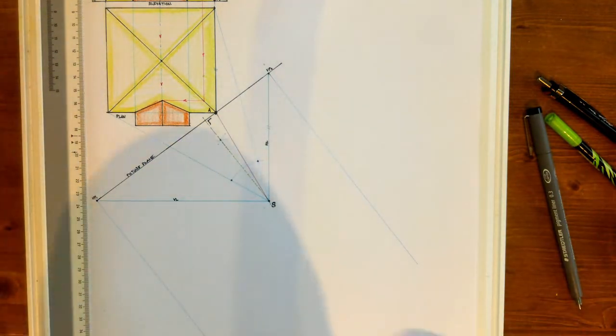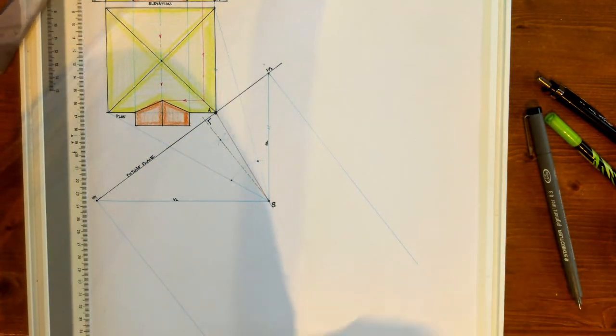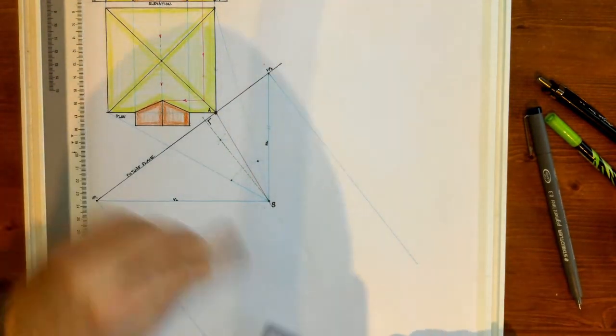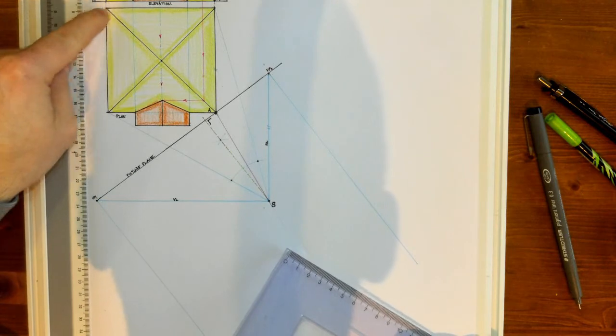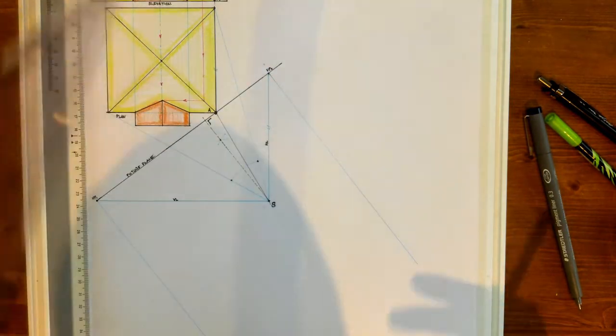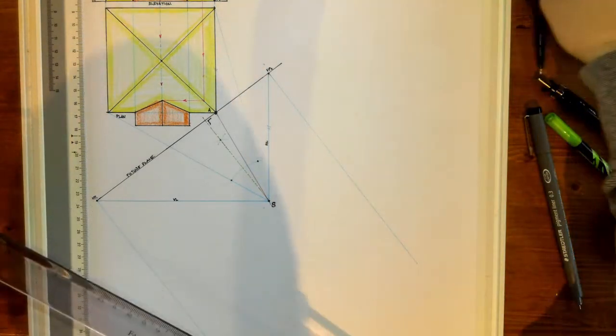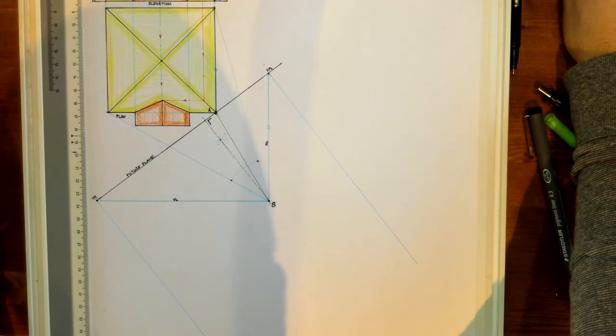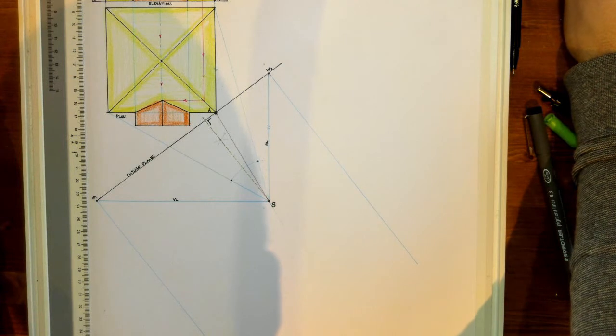Now, what we want to do is down here, we want to set up our ground line. And our ground line was, in the previous examples, the line that we set up just past the furthest edge of our plan view. In this case, what we have to allow for is the information given to us about the horizon line, okay? And we got to think about, well, the size of the structure and so on. But for the horizon line, the information given to us was that the horizon line is 5 meters above the ground line, okay?